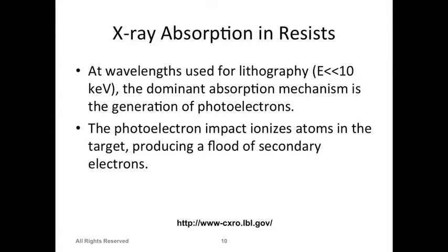If we have a regular photoresist and we shine it with X-rays, they are too penetrating, they will pass through it all the way, and they will generate a lot of secondary electrons. That's how the regular photoresist is used. You shine it with some light source, it provides energy, and then secondary electron generation breaks down the polymer chains, because of heat production or sometimes a chemical reaction.